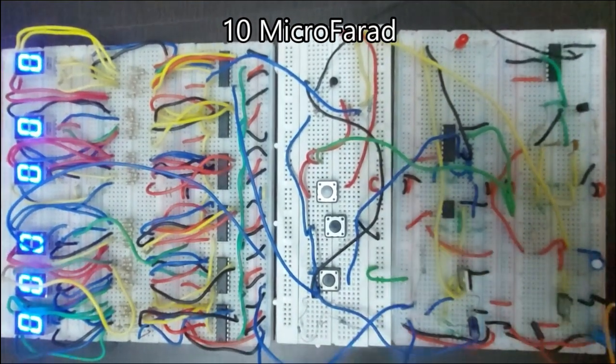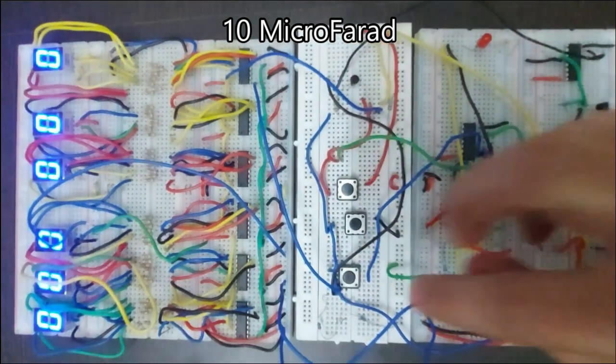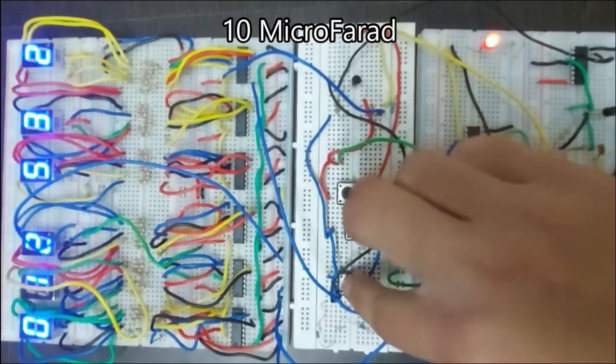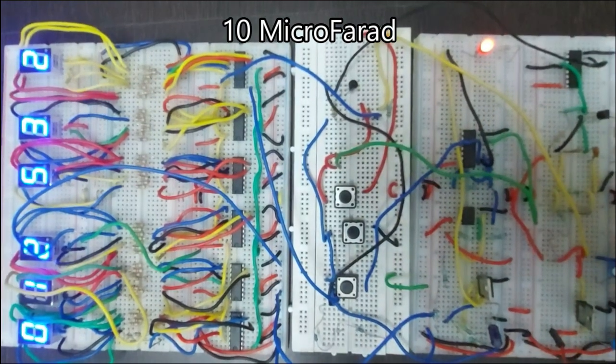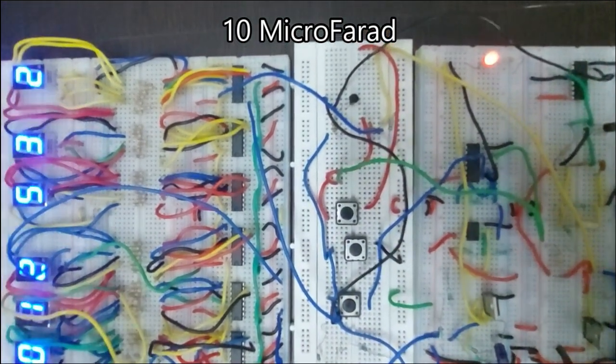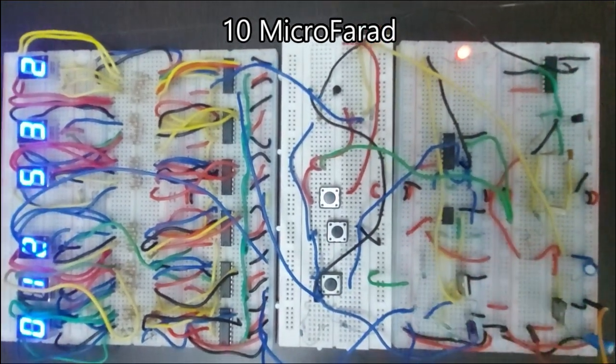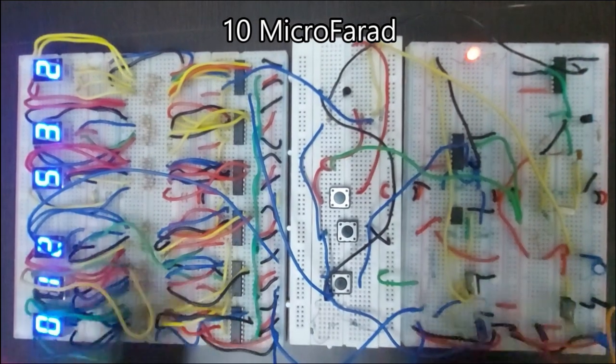I plug in the capacitor. Now we're going to reset the circuit. Now we are going to test it. Here we have 12.532 microfarad, which is a little bit far, but still close to 10 microfarad.